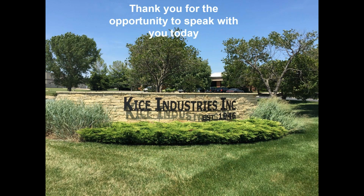It's just that you've probably bought more filter than you need. You've probably oversized the filtration system compared to the process, and you really don't need that much air. You don't need that much cleaning. Now, if you intend to grow in the future, maybe a low air-to-cloth with the intention of increasing later is a good idea. But again, I don't think you should necessarily buy up now and pay for much more than you need.